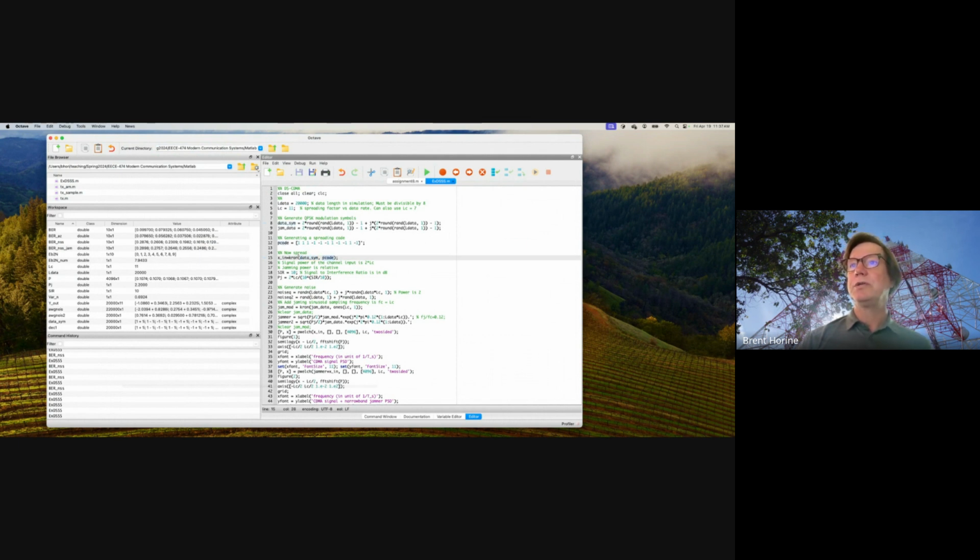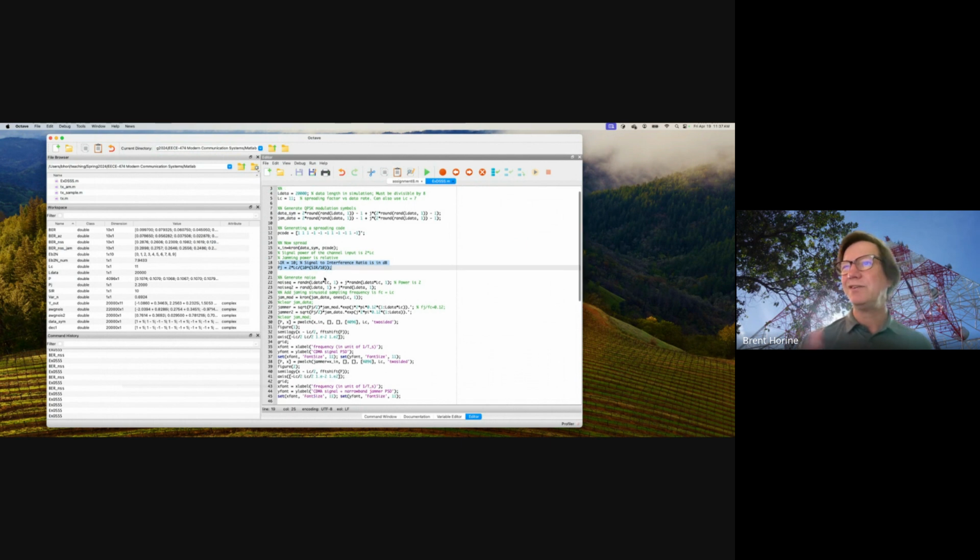So we're going to get each one of the data symbols replicated according to this, right? It's going to be multiplied by 1 or minus 1, and you're going to get 11 of these for every data symbol coming out. So that's spreading this waveform, right? So then we create an interfering signal, and they do some stuff to try to adjust the powers and that type of thing.